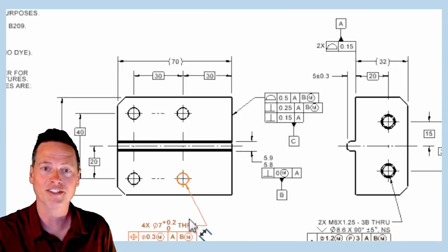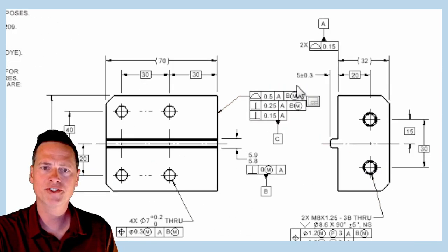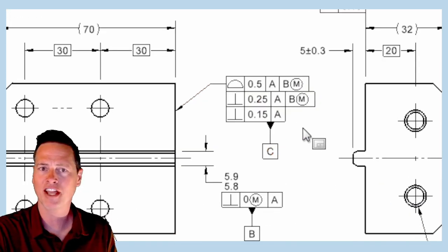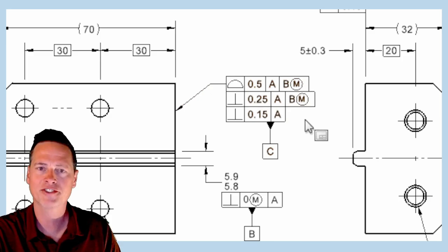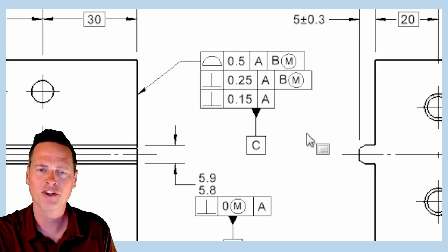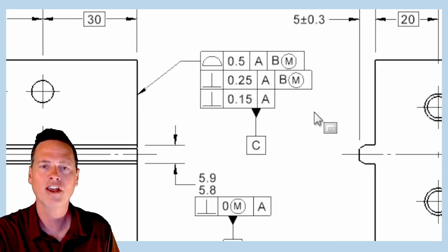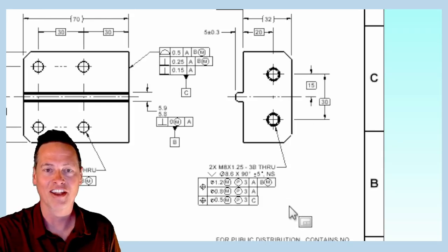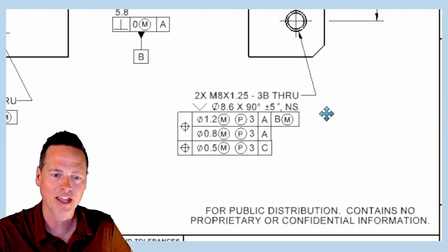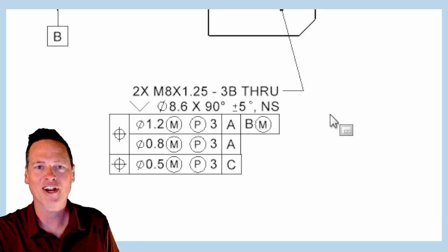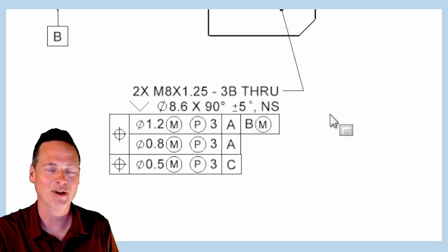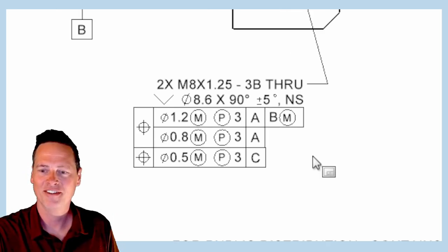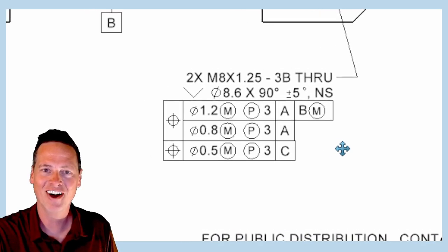It's actually free to slide left and right. And now we're still calling the perpendicular feature a datum feature, and I've added a little bit extra control. So now we're controlling the position with a profile callout, and we have a couple levels of perpendicularity control. All right, and now onto the callout for these M8 holes. I'm worried I'm starting to turn into a one-trick pony for you, but maybe the repetition is good. We have a small pile of positional callouts here.